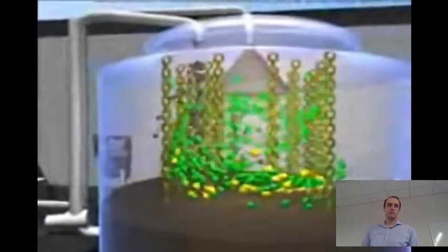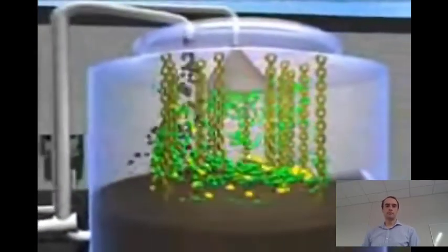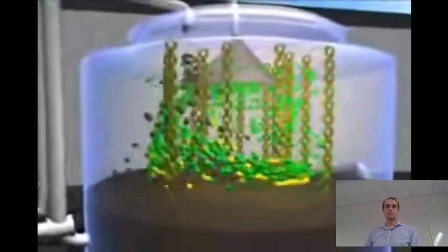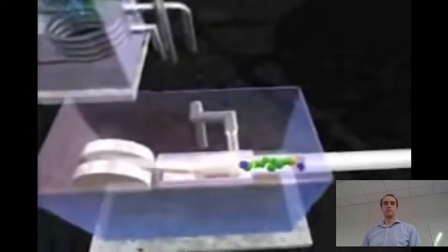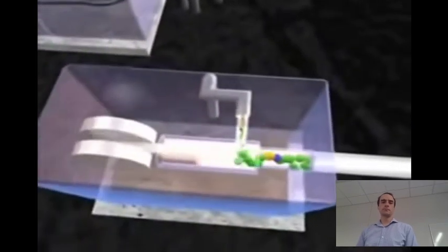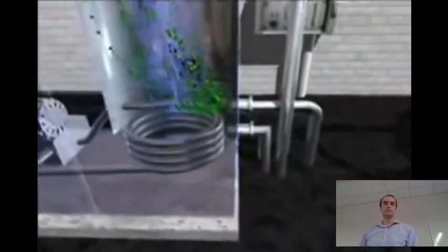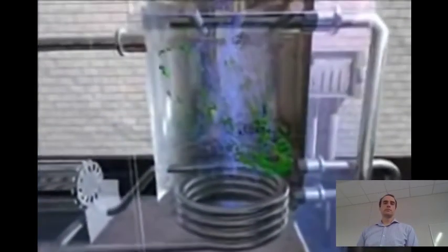By introducing air into the container, certain bacteria cultures are able to establish colonies on the chain. Here they decompose hydrogen sulfide into harmless sulfur and water. The almost unpressurized biogas is then fed into a compressor, where it is brought up to the 70 millibar pressure later required for burning. In order to completely condense any remaining water vapor and to free the biogas from any suspended matter or silicates, the biogas is subjected to a washing and drying process.